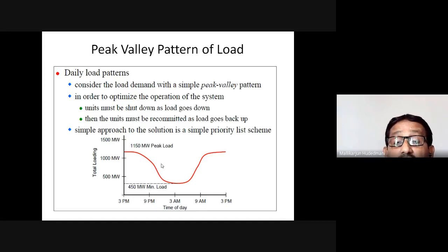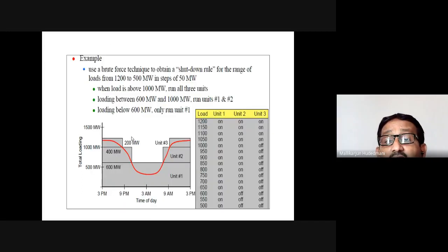So it is an economic scheduling concept, a magnified view of several generators in a station. How the combination of committed generators can cope with your requirement has to be studied by method 1, method 2, like that. The first way which we saw was simple enumeration: identifying the possibilities, and identifying the best possibility out of them for a certain demand, worked out numerically, picking the one which is cost effective in that duration. Then take another example of the same case using the brute force simple enumeration technique.